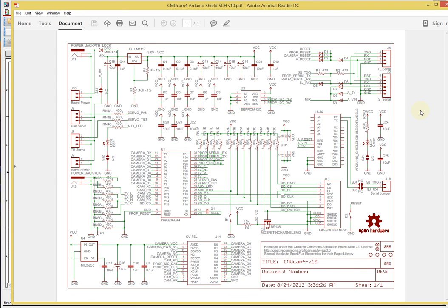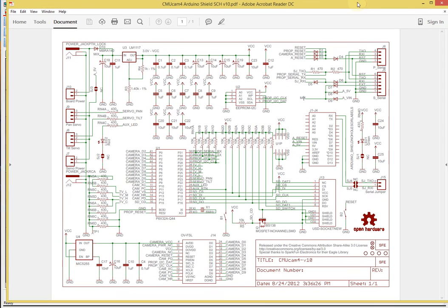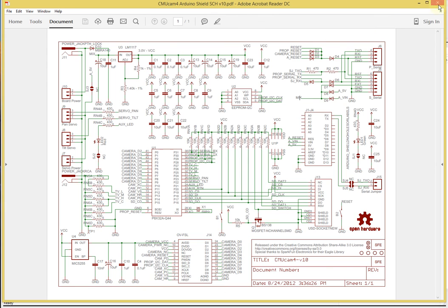Okay, you have pages, spread it out. Put the power supply subsystem in one page, put the digital subsystem in another, put the connectors in another if you need to, or try to connect as much as possible so that my eyes can see where everything goes, instead of my eyes having to search for where everything is. This is not clear documentation, and you should avoid this practice.